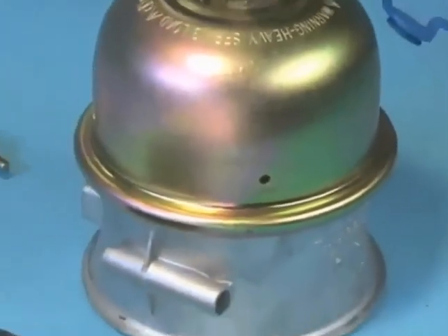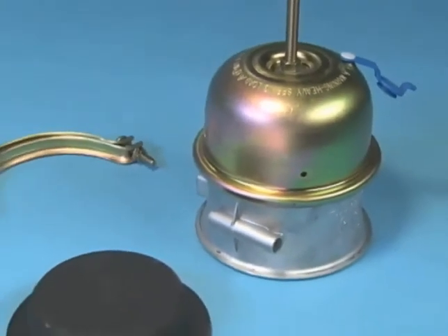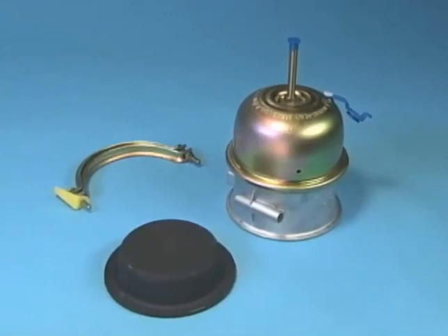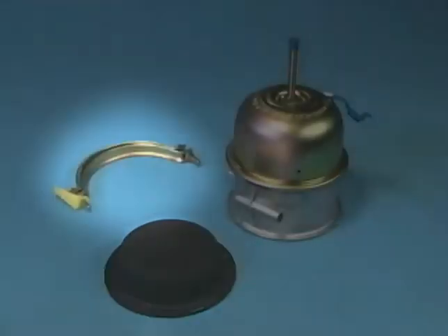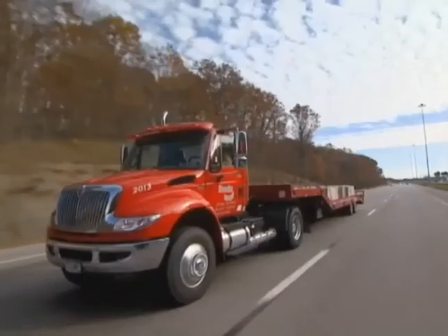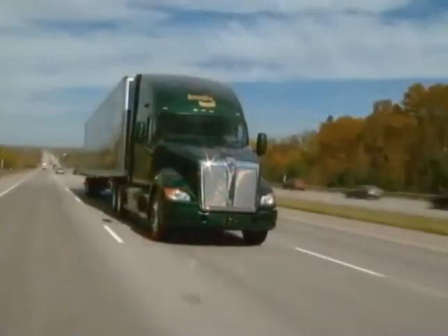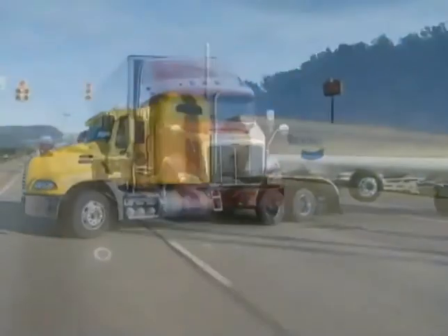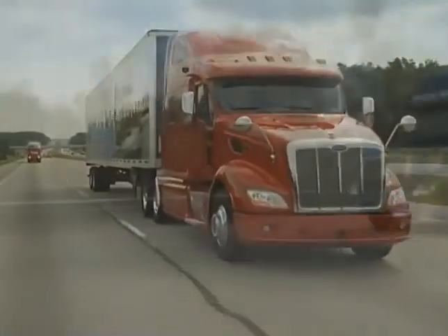Leakage from the spring side of a spring brake chamber should be addressed by replacing the piggyback. Bendix piggyback replacement kits also include a new diaphragm service clamp band and hardware. Remember that air leaks add up to high-duty cycles for your air compressor, and that can lead to premature compressor wear and tear.